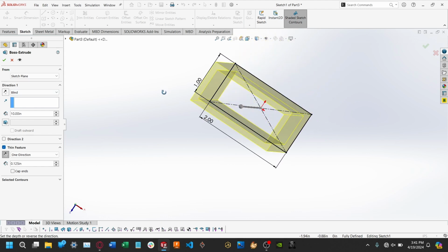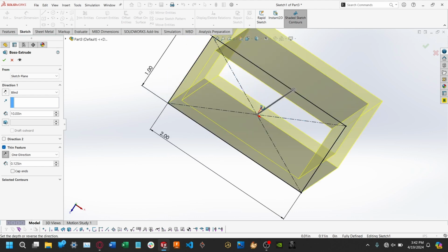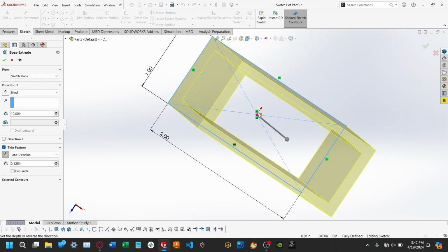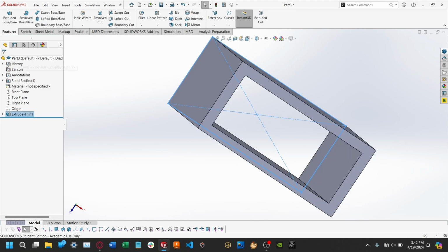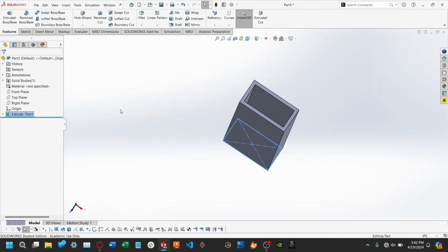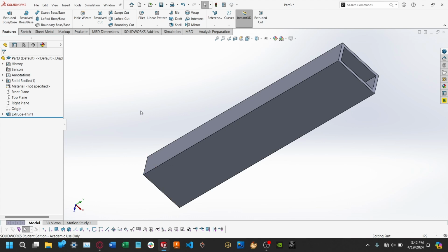Alternatively, you can do some bad CAD practices, like making a cut extrude from the top back down, or making a normal extrude but putting two rectangles nested within each other. We don't want to do either of those. They take more time, and I would believe they also increase file size, and it's easier to do it this way. Now, we hit that, and it's a hollow tube.